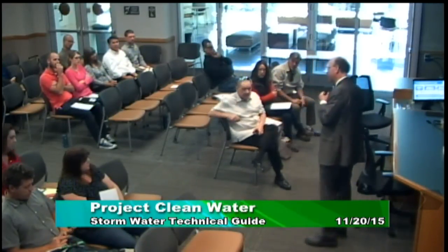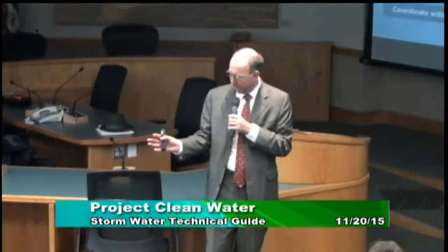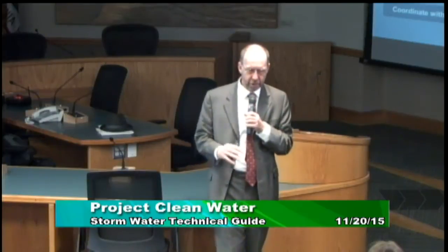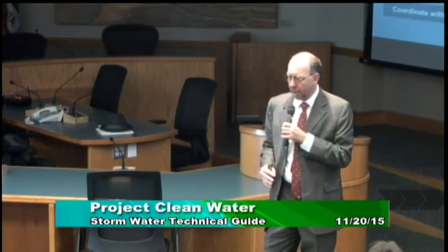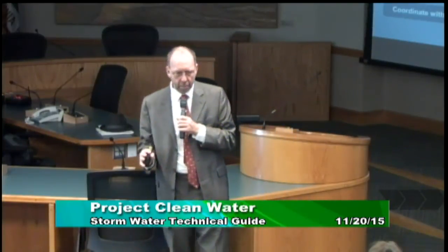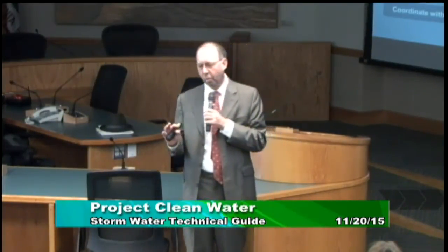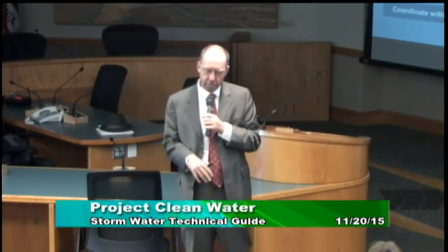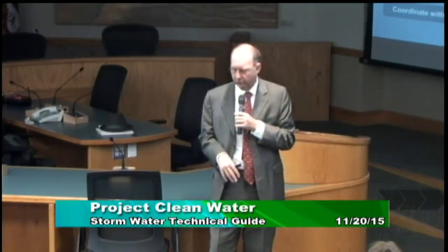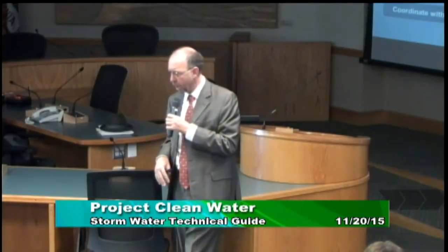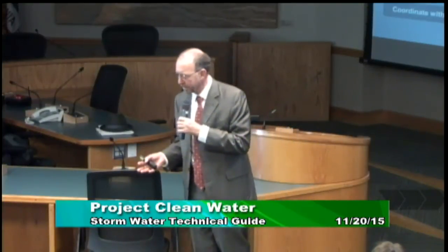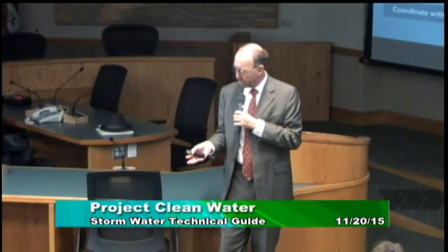Well, frankly, I'll be very honest here. The politics of the situation is that practically what I have seen over and over again around the state is that when that happens, you end up with an agreement: oh, well, we'll let you do an underground vault because it's impossible to do LID with the site design you already got approved, and it would be too much of a burden for you to redesign your whole project and go through the planning commission, which may not want to see you again anyway. So that's the problem.